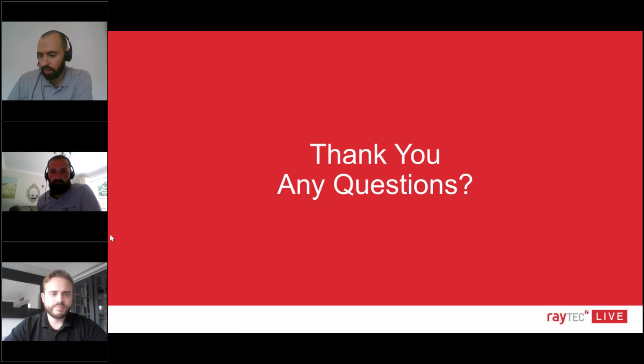Great. And then I think the last one, which was actually a pre-asked question, we don't have a name against this one, but the question was, why do so many manufacturers still use EXD when EXE is now available? I come across this a lot in Europe, and there's a tendency to specify what you've always known and work with what you've always worked with. So many tenders and specifications have EXD on because the guys have always used EXD, and it's what they know and what they're comfortable with.